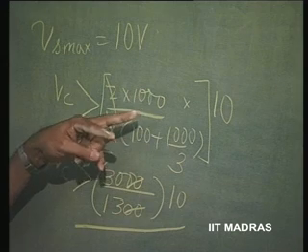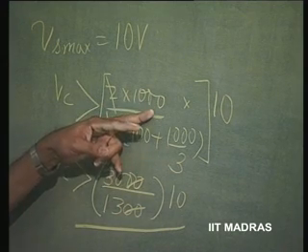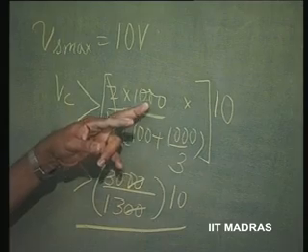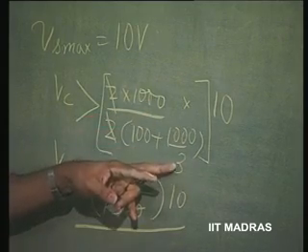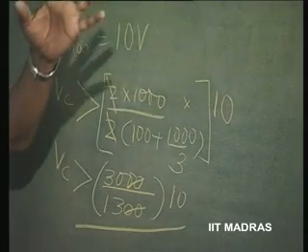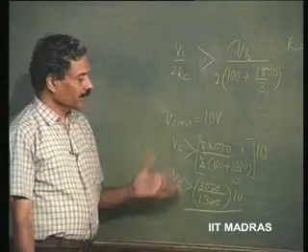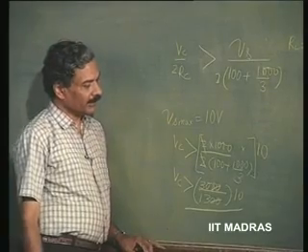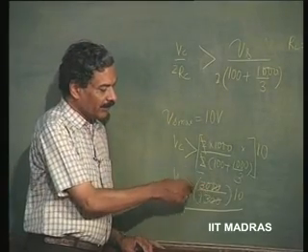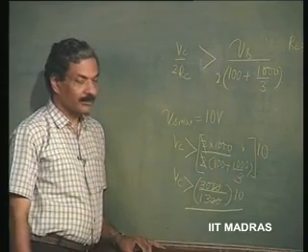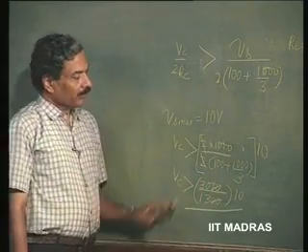If you select the value of Rc lower, then it is going to be lower. If you select the value of Rc higher, ultimately it can be 3 times that, if all Rc's are made the same as RL, okay? And since RL is fixed, we do not have any other choice. So, in this case, it is dependent upon the choice of Rc in relation to RL. So, this is the thing.